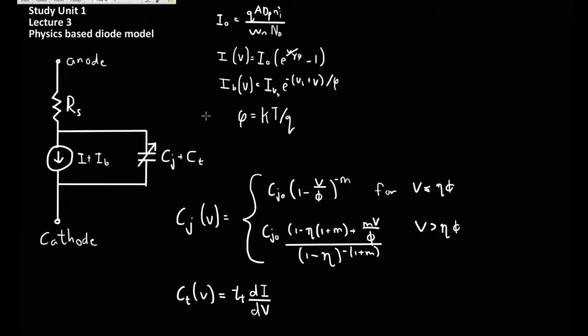The piecewise linear model from the previous drawing is good enough for hand designs and for analyzing circuits, but in order to correctly simulate the diode, a more comprehensive model is required. The model shown here is a physics-based diode model, which is often used to simulate diode behavior, especially when using a package like SPICE to simulate the diode.